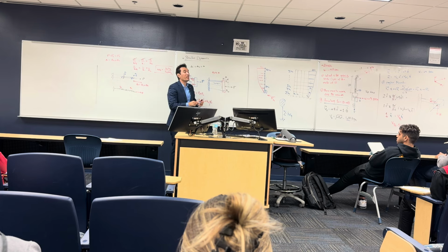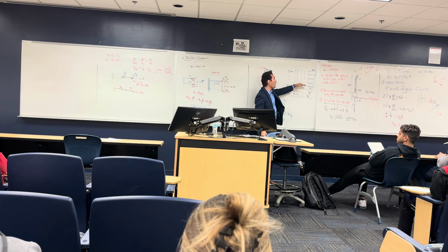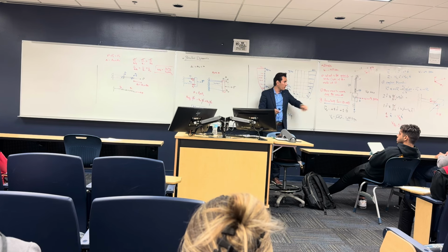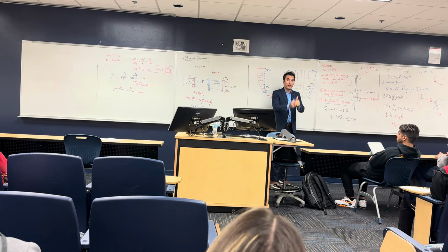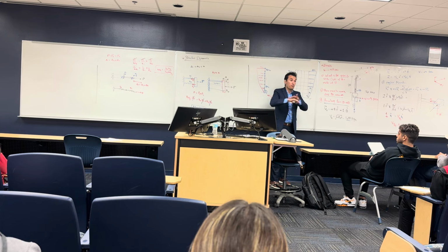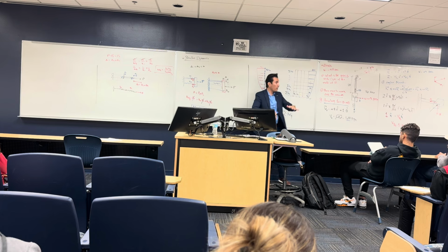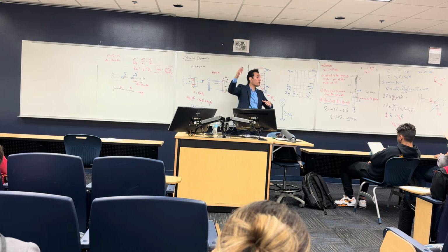So what we did right now, we condensed a very, very complex system, like a building that has hundreds of thousands of degrees of freedom. Because right now we are not talking about degrees of freedom in the X direction, this is 3D. So each point in this building, each corner, has a degree of freedom in the X, in the Y, in the Z, and rotation about X, rotation about Y, rotation about Z, multiple degrees of freedom. And each story has 100 points. And each one of these 100 points has 6 degrees of freedom, and we have multiple stories.